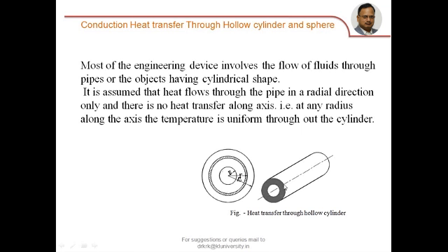Suppose the temperature at this point on the outer black circle is say 100 degrees centigrade. Carefully follow. At this point it is 100. The temperature here is also 100, here also 100 degrees, here also 100 degrees. That means I am not considering the variation of temperature in the theta direction, because all along this outer circle surface the temperature is 100 degrees only.